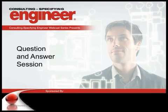Dean, question for you from Paul Luoma from Reston, Virginia, asking, when using a make before break ATS, do the generator and utility contributions need to be added to determine the fault current? That's a good question. In many cases, that's an ambiguous question. I think the best answer is probably to ask your authority having jurisdiction. I've seen cases where you can not account for it, and I've seen cases where you are forced to account for it.